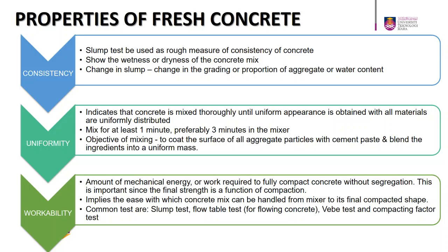The concrete will be mixed for at least 1 minute, preferably 3 minutes in the mixer. And what is the objective of mixing? It is to coat the surface of all aggregate particles with cement paste and blend the ingredients into a uniform mass.